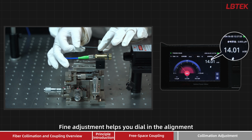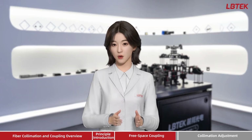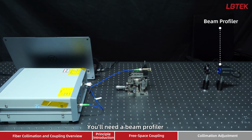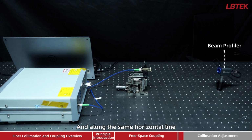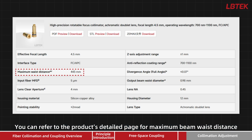Fine adjustment helps you dial in the alignment and also match the spot size to your needs. While for collimating fiber light into free space, you'll need a beam profiler, also called a beam quality analyzer, and a focusing lens. The laser is fiber delivered. Set up the optics as shown. Keep everything at the same height and along the same horizontal line. Place the beam profiler at the collimator's reference distance. You can refer to the product's detail page for maximum beam waist distance.